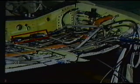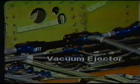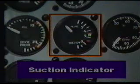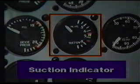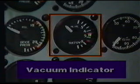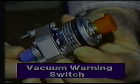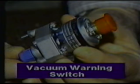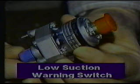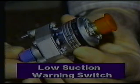The unit that creates the vacuum is called the air ejector, or sometimes called the vacuum ejector. The indicator in the instrument panel is either the suction or vacuum indicator. The sending unit, located in the left-hand wing root, is the vacuum warning switch, or low suction warning switch. This unit controls an amber annunciator low suction light.